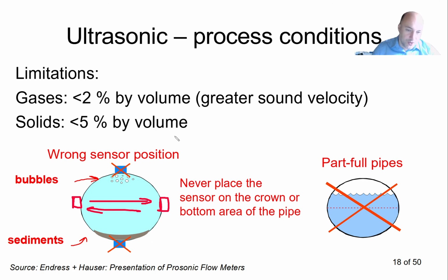There is also a limitation by volume of how many gases and solids we may have in the liquid. So it is said that approximately at maximum 2% by volume of gases is allowed in the liquid, because if we have a gas, we will have a different sound velocity in the gas than in the liquid itself.